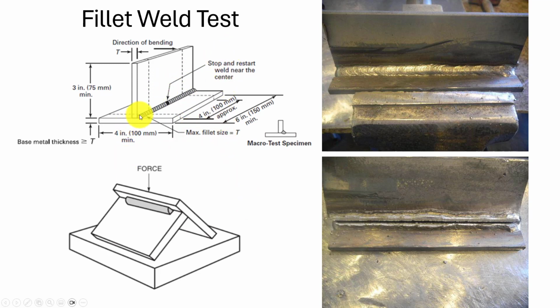The welder will have to set up the machine. They'll have to conduct a series of welds like this, and then load it in a machine where we just come in there and press it, and they can use a standard shop press for this and see where the weld breaks and how much load it held, for example. And here we had a nice weld break across the throat here, so this would be a good weld. And you can see the weld looks really nice there.